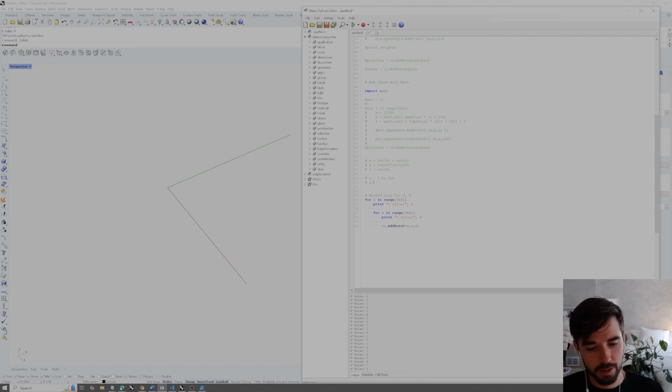Our v domain, based on Joseph Choma's equation, is 0 to just 1 pi. So 1 pi is equivalent to 180 degrees. In order to make that translation, we need to determine a different domain than 0 to 360. If 0 to 360 equals 0 to 2 pi, then our u value is already acceptable. In fact, we could add the beginning value 0 to 361, iterating all the way up to 360 degrees. And then we just have a step of 1, so that will work for that domain.